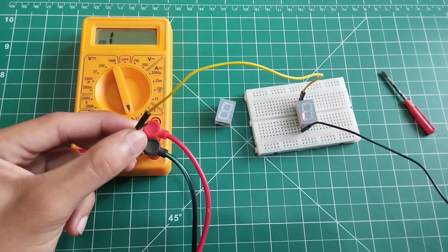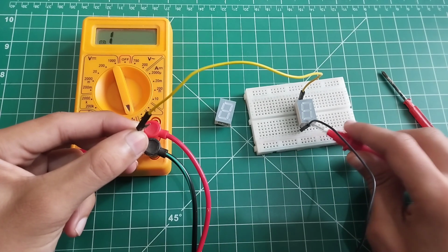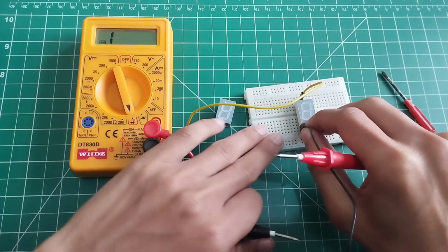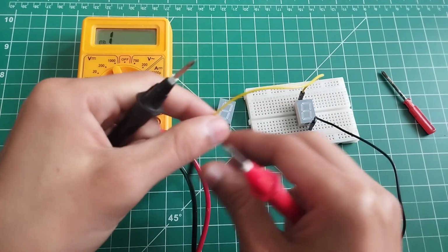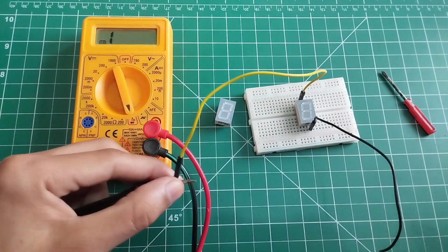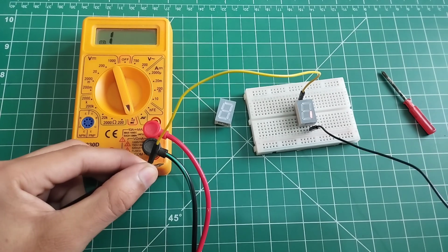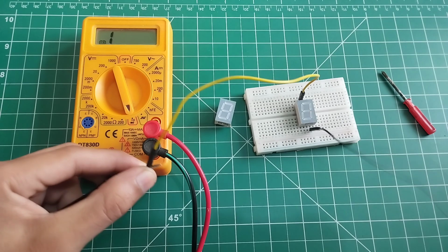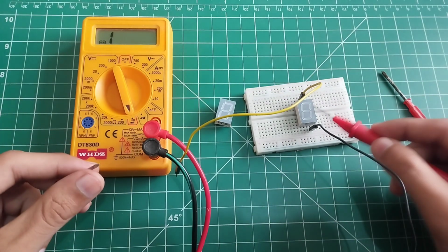So you can see one of the 7 segments is turning on. So it means that the leftmost terminal is connected to this LED, right? And similarly, if I remove the jumper wire and connect it here, and again repeat the procedure, you will see that another LED will turn on. So in this way, by removing the jumper wire and inserting it at each terminal, you can test each of the 7 segments. And in this project, I am going to use this common cathode type.